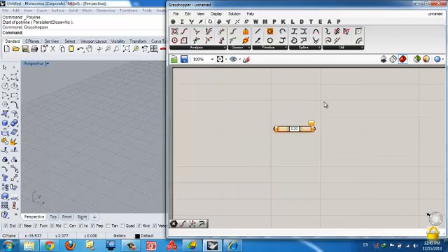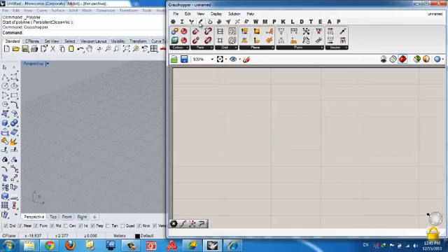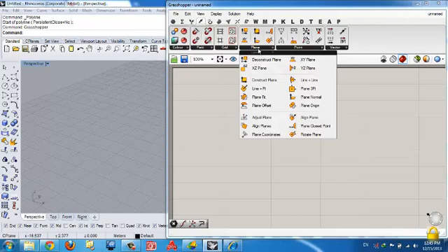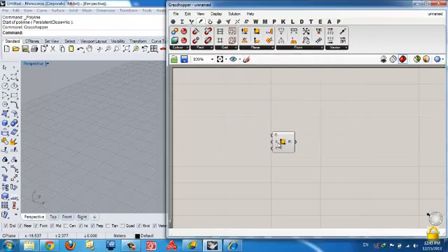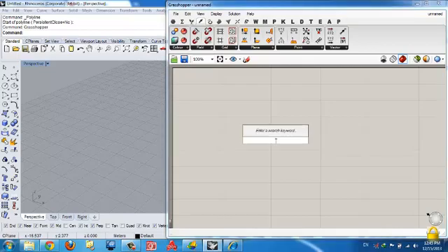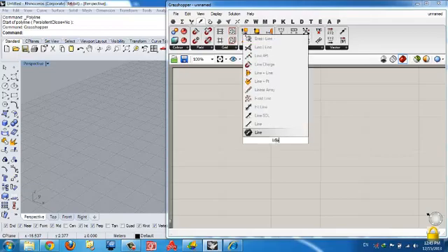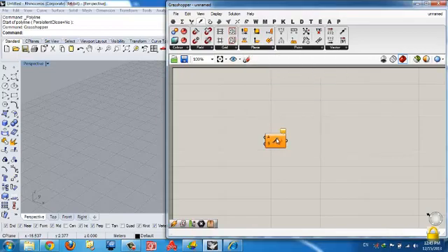And mainly we go for the tools in two methods. One is the typical one, that you just search for the tools, bring them up, activate them and feed them, and another one is just double clicking on the canvas and typing the tool you want. So Grasshopper will give you some suggestions and you can click it on the canvas.